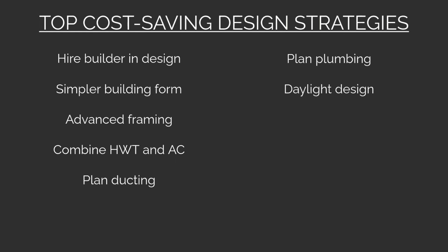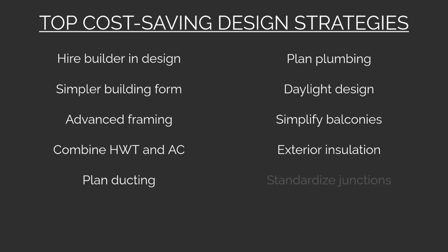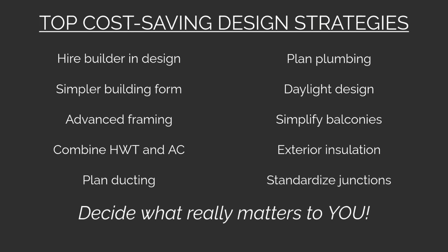Develop a daylight design strategy. Simplify the overall structure of decks and balconies. Fully exterior insulation with a waterproofing membrane. Standardize the building junction details. Decide where spending money would make the most difference for your enjoyment of the house.